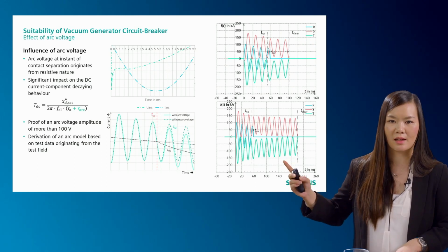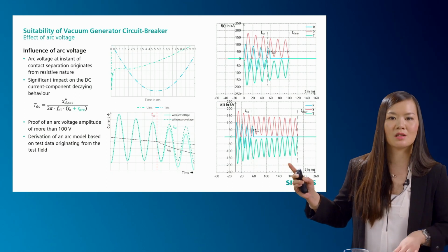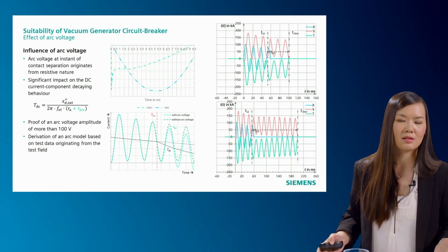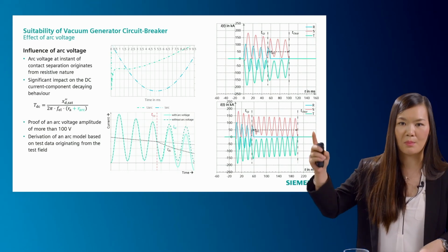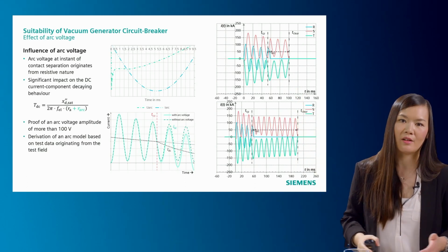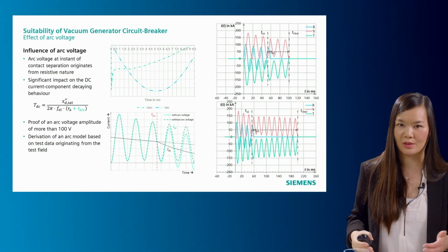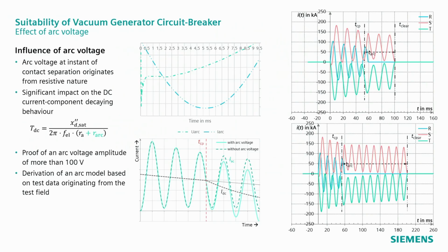And as you can see in the lower part of the simulation of the same set, you do not consider any arc voltage here. And of course, that is the normal simulation that any consultant can do. But we are the manufacturer of the vacuum GCB, so we have the internal knowledge about the characteristic of the vacuum arc, and we implement that as requested by the standard to provide our customer with the new simulation, including the effect of the arc of the GCB.